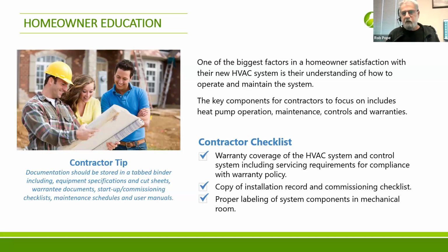Where the filters are, how often to change them, what kind of filters, and where to get them from. Here's your paperwork for warranty. Here's the commissioning checklist. Here are the user manuals. Here's the maintenance regime that you should be thinking about having us or somebody else do. Here's how to operate the system, here's the thermostat and how to do your programming, and what's the difference between auto and on for your fan setting, for example. There's a whole bunch of that stuff you need to go through with the homeowner before the job is really done.